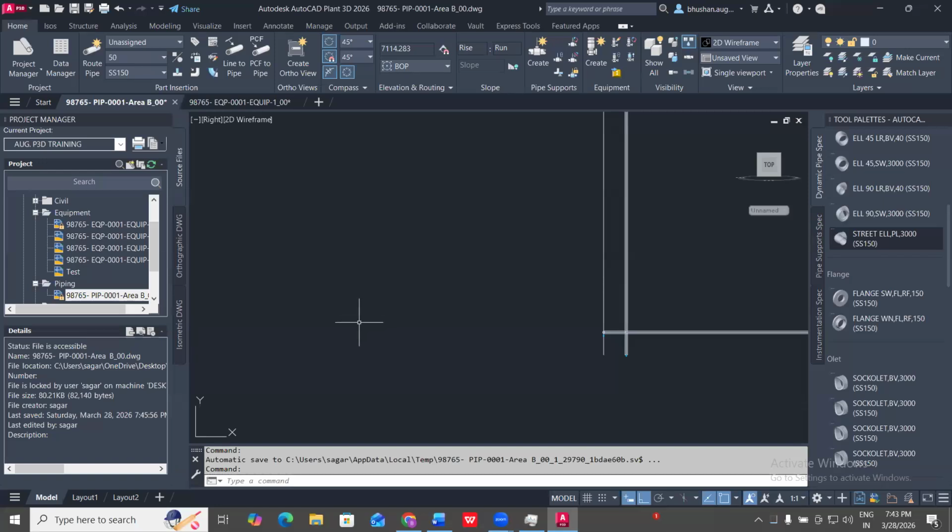It has a very specific bending radius defined by the standard, usually called a long radius or a short radius. A long radius elbow is smoother and causes less pressure drop. A short radius elbow is more compact.